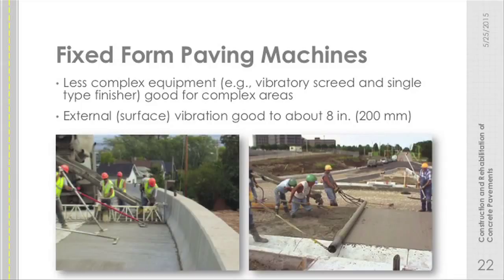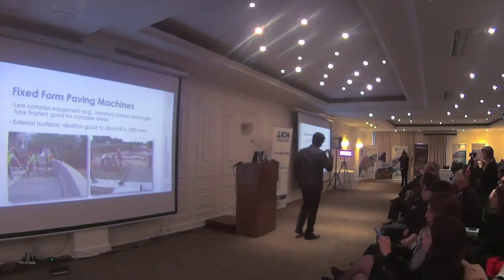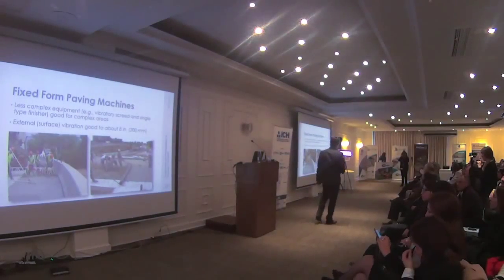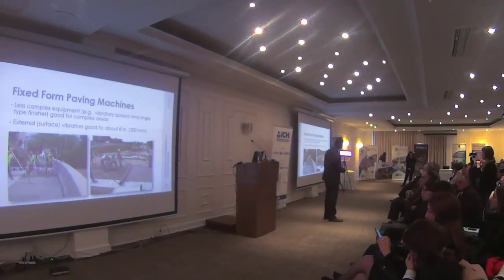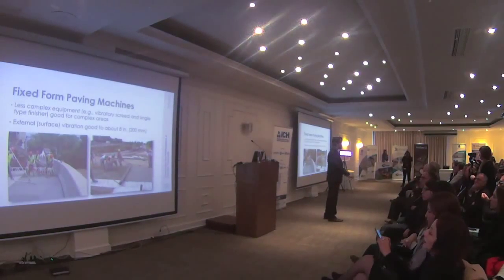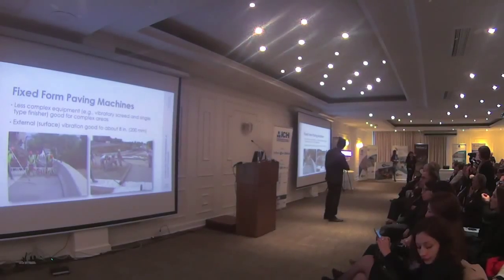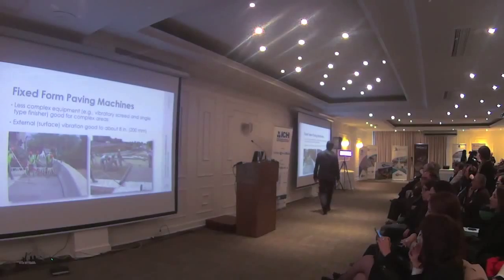This looks to be on a bridge where they have that truss cantilevered out. Same idea. They're supplying concrete, they're spreading it around, leveling it out, and then striking it off. So these sort of screeds and trusses are good for very odd, complex areas. We would not be able to get a slip-form paver very easily into this space unless it's a sidewalk paver.